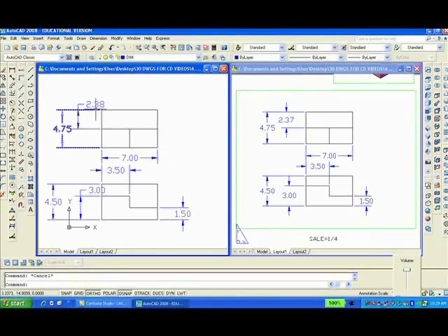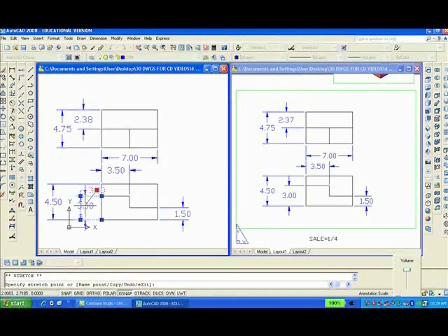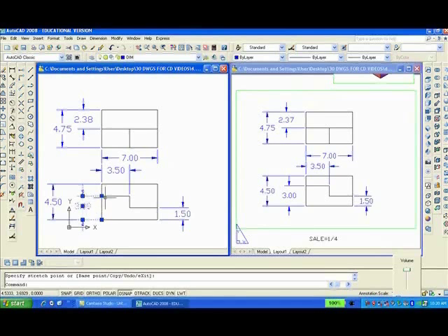These don't look too good, so I'm going to change them. I'm going to take off the object snap and the ortho. I'll click on that dimension, grab the grip and move it in here like this. Pick a point there. That looks better. And I can do the same with this one. With the grip, grab it and move it where I want to put it, like there. Hit escape. Or I can even center it better since the O-snap is off. So that looks better.